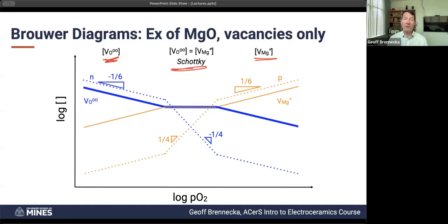So a lot of times we don't necessarily need to run hydrogen or carbon monoxide into our furnace to pull oxygen out, to create oxygen vacancies, to get to low PO2s. We can do it just with nitrogen or just with argon, because the partial pressure is the part that really dominates how those individual species in your sample are going to react. That's another piece to keep in mind.